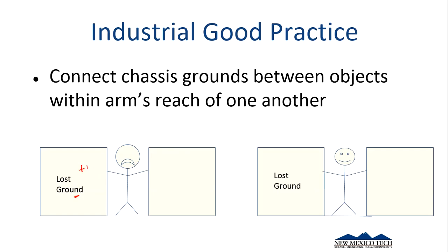Maybe this is sitting at 120 volts now, but this one has a good ground. So now, when you walk up and touch the two frames of these things, you end up having this path, and so he's unhappy about it. It kind of looks like a mustache, but he's supposed to be frowning. But you end up with this current path through you, so that's no good.